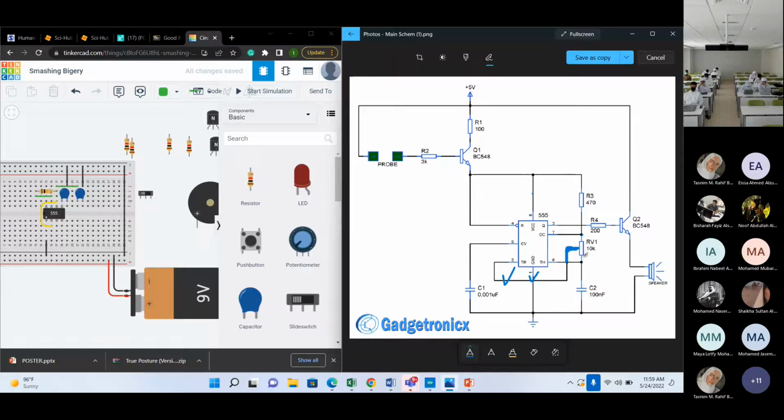All right, then what about the connections of pin number 6? We have this here to the capacitor, so pin number 6 to the capacitor to the ground. Did we do this? So we already did this. Excellent. Then the last one, what do we have? Pin number 6 to a resistor and then to pin number 7. Did we do that? Yes, we already did that. Excellent. Okay, so this one is done as well. Which one did we also do? The pin number 5 to the capacitor to the ground, right? Does any of you have a problem, guys, with this so far?